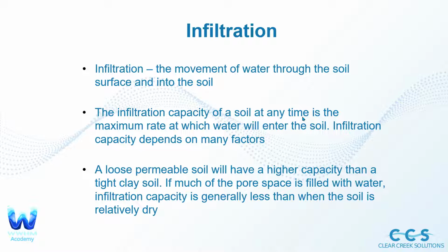So let's start talking about infiltration. What is infiltration? Infiltration is the movement of water through the soil surface and then into the soil. If you think about it, if we have some regular grass and it rains on it, the water's just not going to pool up on the surface and run off, right? That's what it does for impervious surfaces.